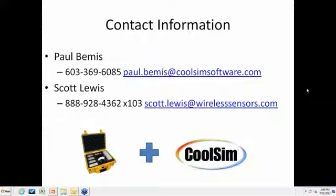And then we'll put a couple of temperature and humidity sensors in the hot aisle if it's a hot aisle configuration, and then an inlet and an outlet on each CRAC. And that constitutes one rack pack. It's a place to start, and you get valuable data with that kind of granularity. If you feel like that's not enough, you can always add sensors. If you feel like that's too much, then you can spread them out a little bit, and that might cover a lot more than 1,000 square feet.